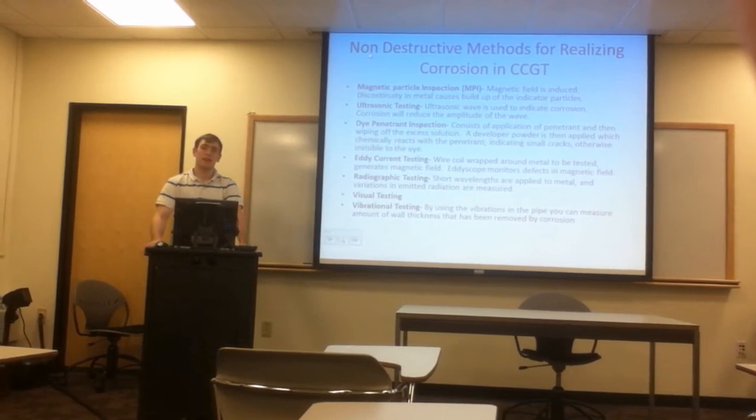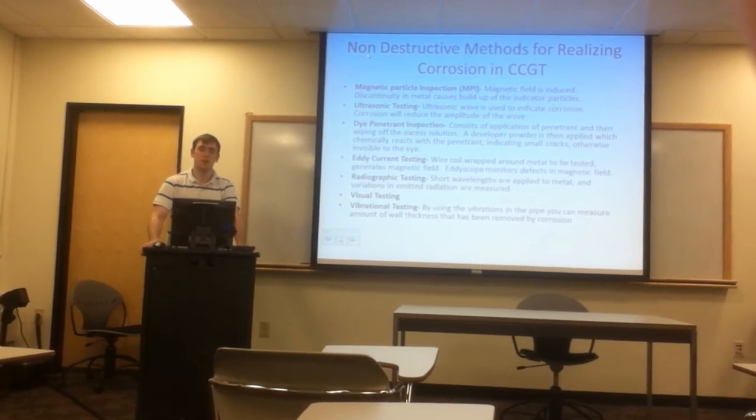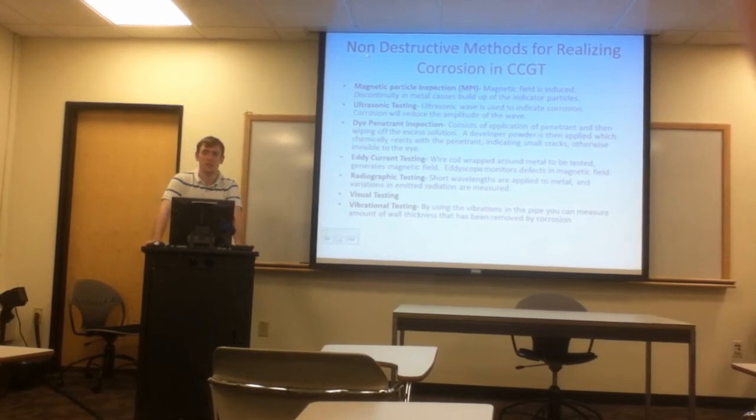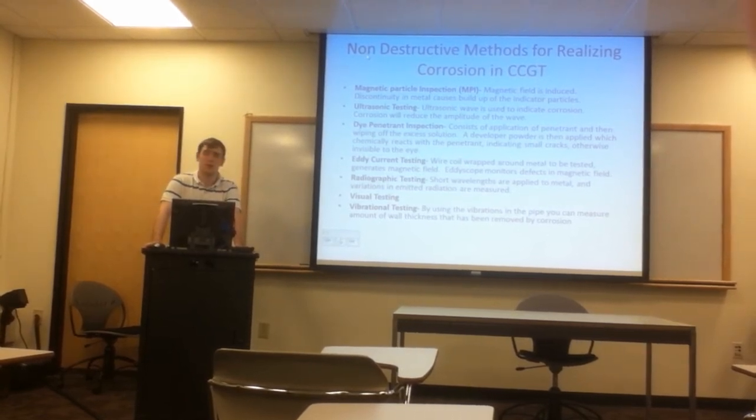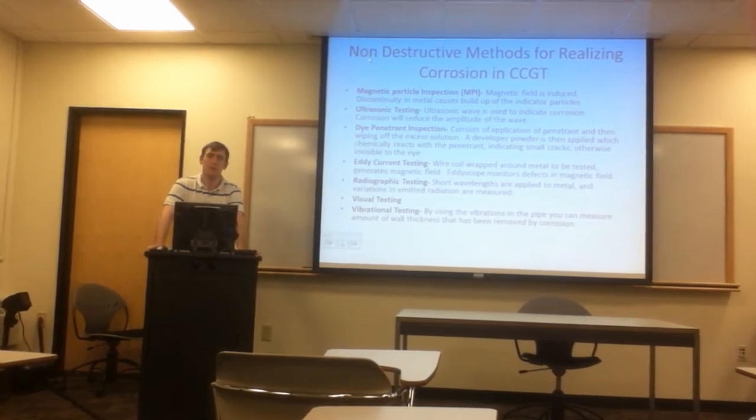For the heat recovery steam generator, vibrational testing is a very important means to determine the wall thickness of the pipes. As the pipes corrode over time, their vibrational frequency changes. This can be measured and monitored and used to determine how much corrosion is taking place and if the pipes are still safe to use.